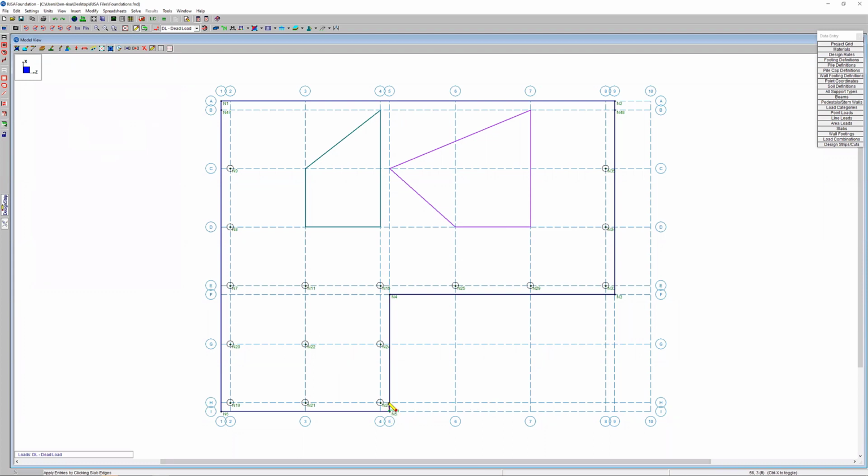So I've selected the bottom half of this edge, which ties me to the starting point, N5. If I want to do that, I can start drawing wherever I want, as long as I end at another part of the slab. So I'm going to go to here and to here and to here, and then I'm going to go back to N3. And so then I can really quickly and easily shift or manipulate that edge of that slab, basically saying, okay, I started at N5, and N5 is that beginning point, and then I can click wherever I want between that beginning point and wherever I choose to end. In this case, I chose to end at N3 to then redraw that edge.